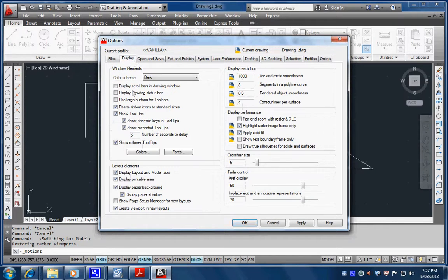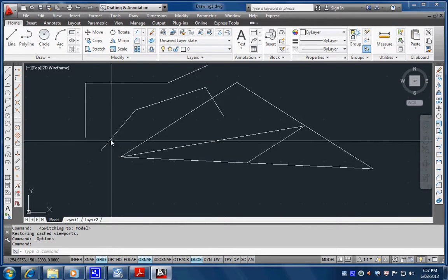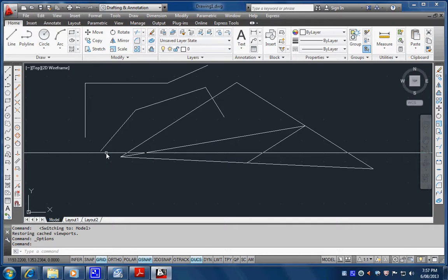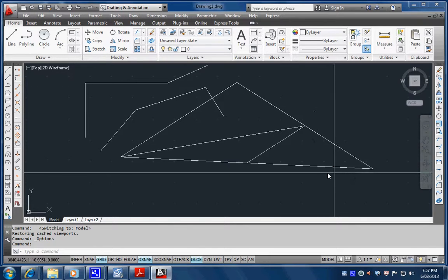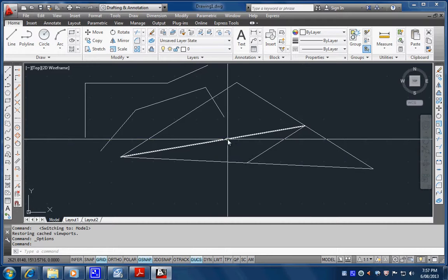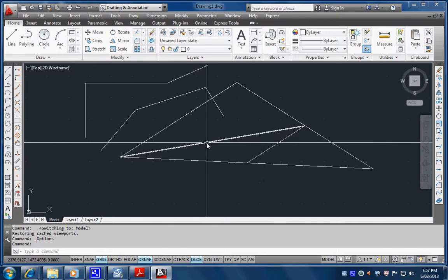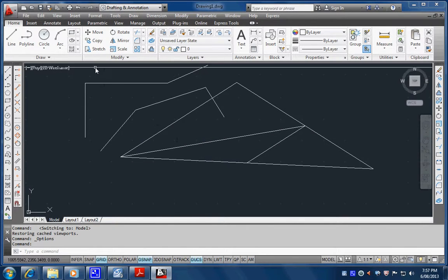While you're here, I also like to do this for me, and this will make more sense later on when we're doing third angle projection, doing elevations. If I make the crosshair 100%, it will give me this. Some people are not used to it, but I find it useful to line things up so I can see that my floor plan or top view lines up with my bottom view, or across to my right hand side view. Just by eye, I can quickly see if things line up very quickly. So I use a 100% crosshair by default, personal opinion though. So that's that there.